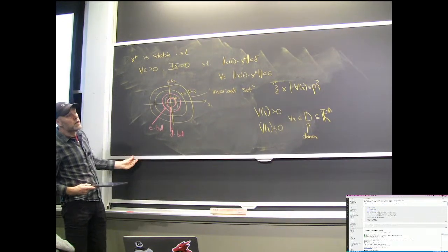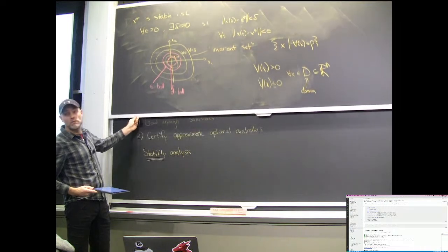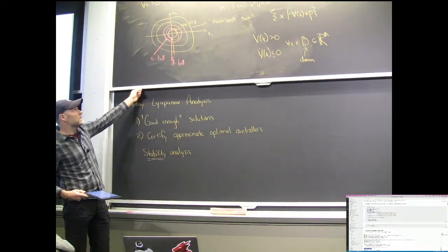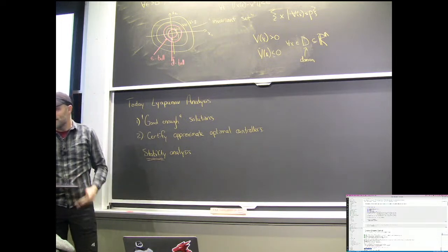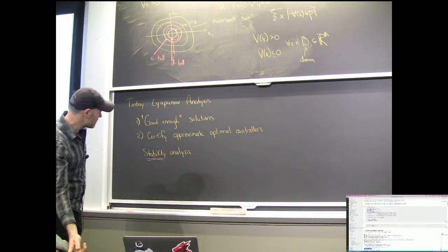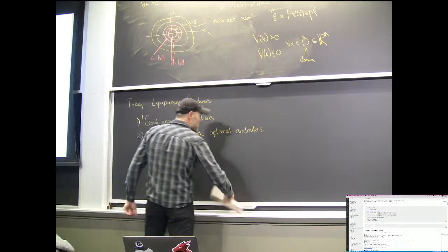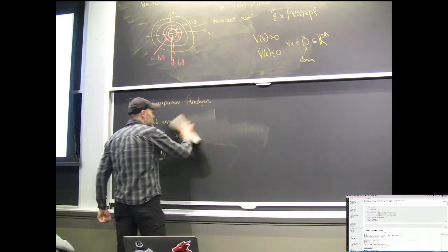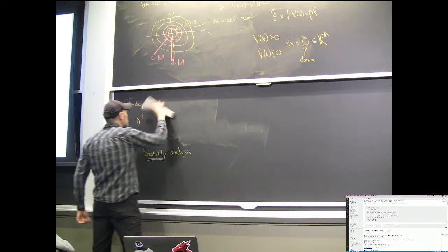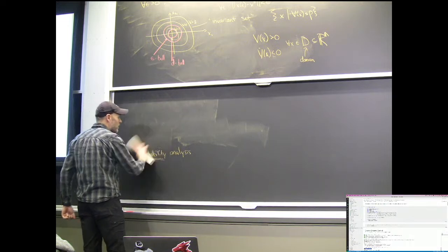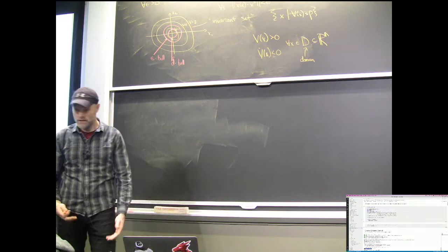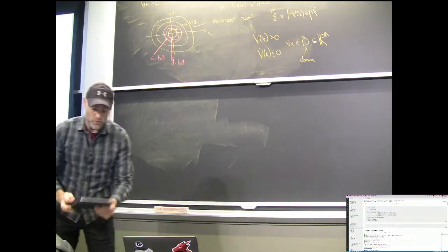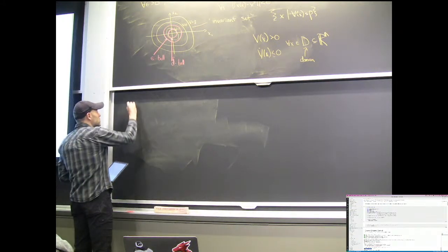Okay. We know that the pendulum is not just stable in the sense of Lyapunov, it's actually stable asymptotically. And it would be kind of a bummer if all this Lyapunov stuff didn't help us also talk about those other types of stability. Turns out a very minor modification allows you to talk about asymptotic stability or exponential stability, right?